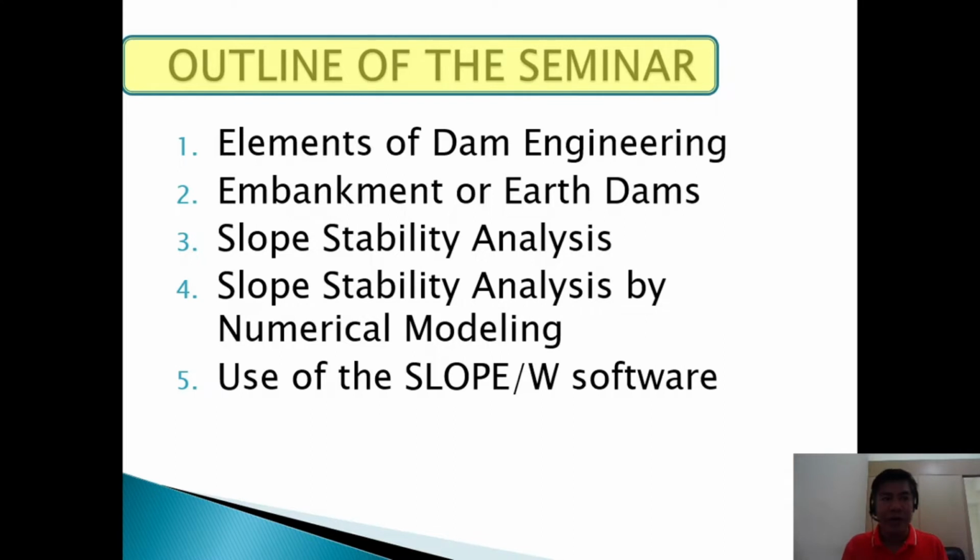It can also do seepage analysis by water flux calculation, the flow nets, and the pressures in the body of the dam and below the body, which is the foundation. It can also analyze possible liquefaction. It can map which part will have liquefaction after an earthquake event, so it is part of an earthquake analysis. There's a lot of things that the software can do.